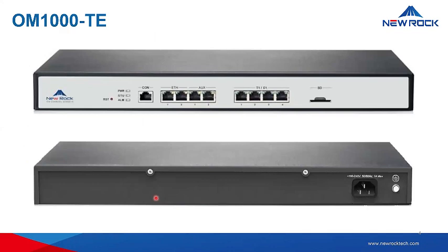Okay, so let's go over the equipment structure for the OM1000 TE. On the front panel, you can see here the reset button. Basically, you need to press this for more than 3 seconds, and the factory settings will be restored. And we have the alarm indicator for power. When it is steady green, the power supply is working. Otherwise, if it's red, the supply is abnormal. So it's very important to see this status during the operation of the device.